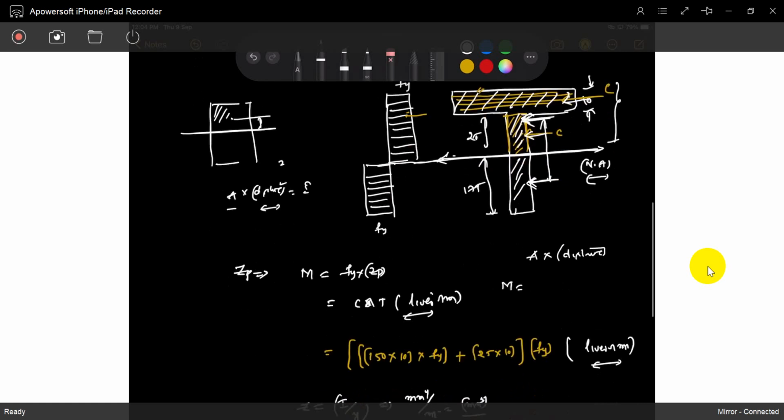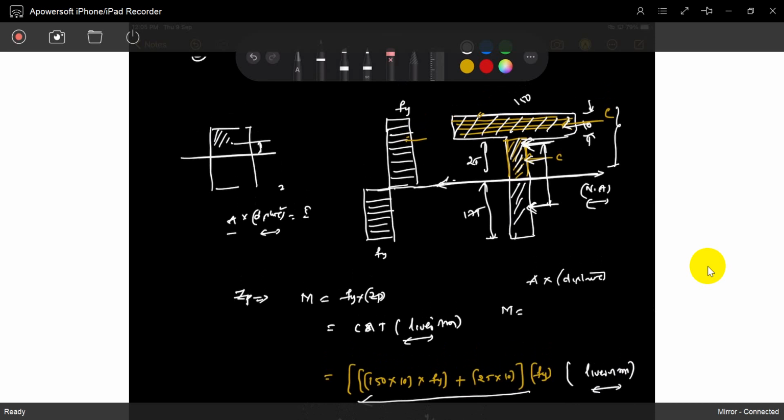See, this is the correct way to find the compressive force or tensile force. Both are equal. No need to find the compressive force and tensile force separately, because the neutral axis divides it into equal areas. Top area and bottom area are equal, so area multiplied with y, Fy, we delete it. So there is no need of Z. Finding the lever arm is difficult because the top has a different cross-sectional area, so you have to find the CG again, and that is the lever arm.